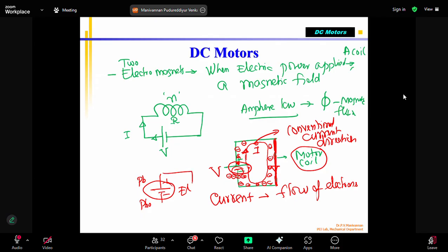Today, tomorrow, you go and measure the voltage without electrolyte. In the battery factory, that's what they do. They make the battery casing, build all these things, and they don't fill the electrolyte. They send the batteries to the supplier where they are selling. Correct? Nowadays it is already pre-filled because this is a different type of battery. But basically, if I go to a battery shop, once you place the order and pay the money, he will fill the battery with the electrolyte. Electrolyte is nothing but 80 to 85% of water, pure distilled water. It should not have any contamination. And the remaining 10 to 15% is sulfuric acid, correct? Pure sulfuric acid mixed in. Then it becomes diluted.